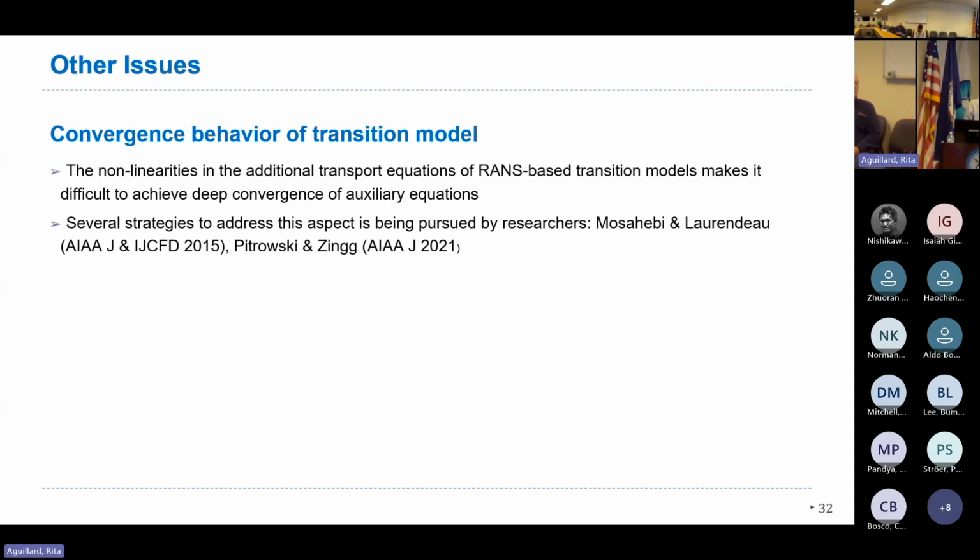Whereas for PDE-based methods, the current guidelines we have identified within our group for subsonic flows is Y plus of 0.5 and smaller. Also for airfoils, you would have to make sure that you have adequate resolution in the leading edge and trailing edge regions. And if you're having separation bubble-based transition scenarios, you would want at least 3 to 4 points within the bubble. That kind of helps.